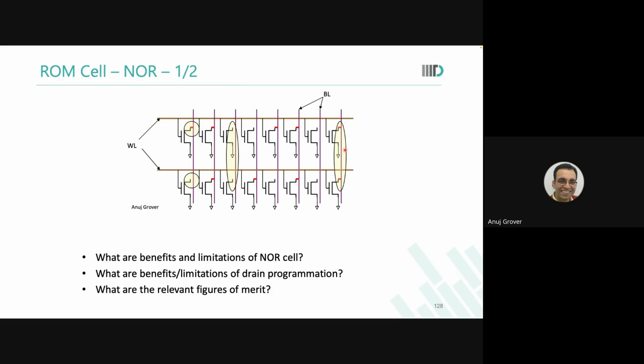So the seemingly power gain, that if capacitance is reduced then power will be lower, is also not there, because now I am discharging it more. The delta V for which this bitline will discharge will be more. Because power is not a function of bitline capacitance in the memory array. In the memory array, power is a function of the duration for which word line is on.